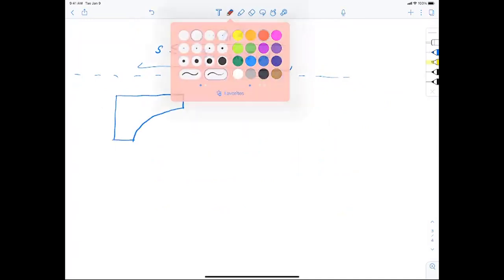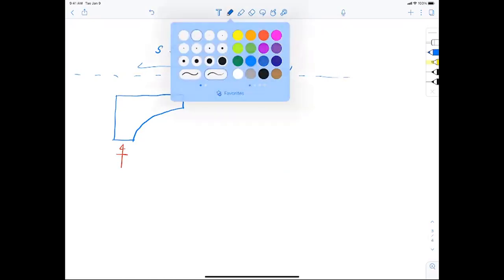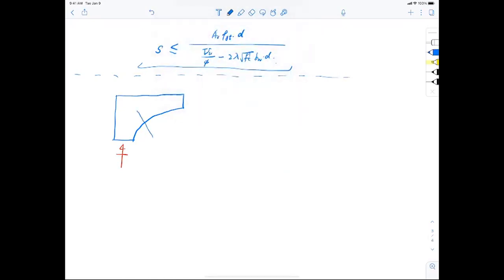And I use the same free body diagram. And I started thinking, what if I want to do inclined stirrups? That means if I arrange my stirrups like this. Is that even legal? Yes, of course it is legal. I can do whatever I want, right? If I have the money, I will just ask the guys to fabricate like that because that can accommodate some seismic resistance.